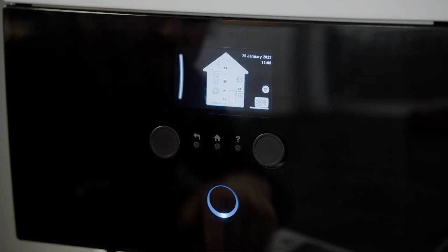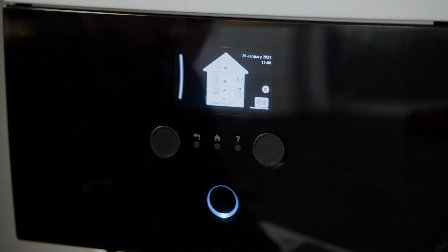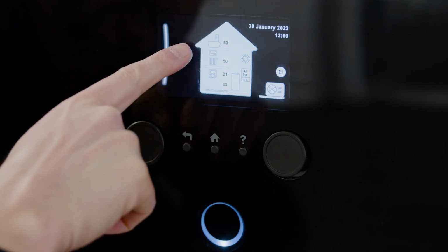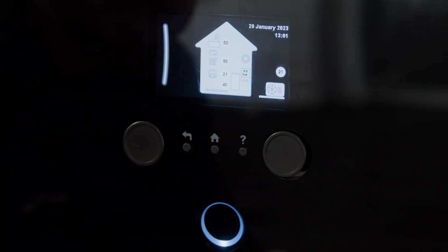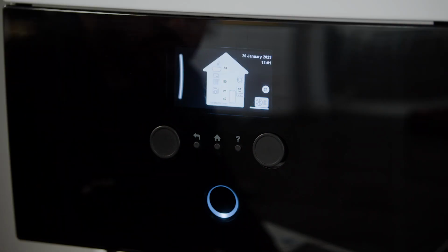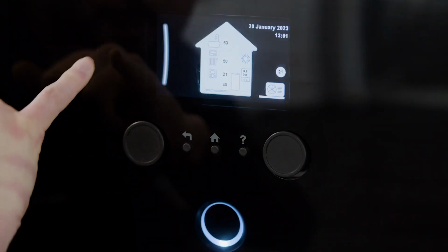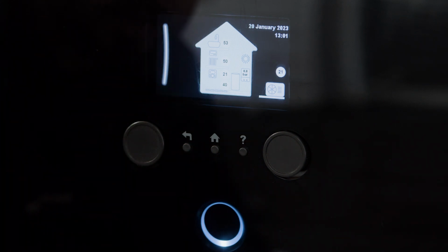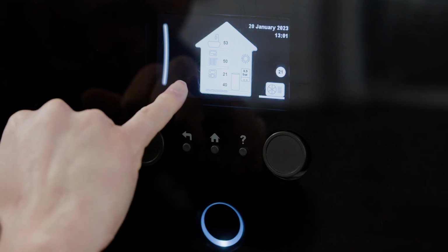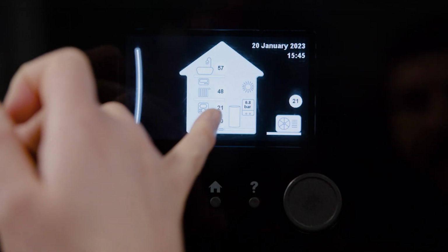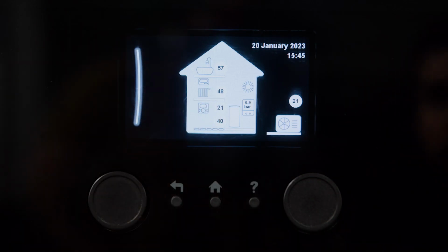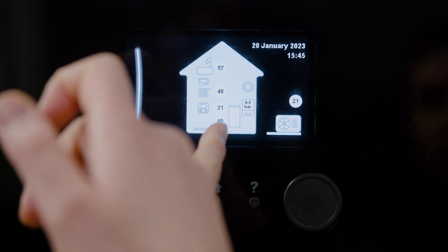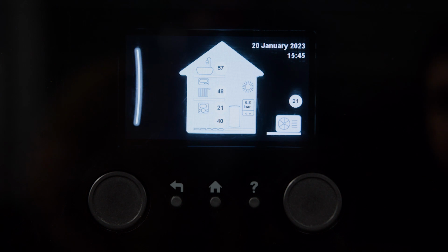There are some sensors within the system, which means that you can see the status or the temperature. For example, next to the bathtub you will see a temperature of 53 degrees. This indicates that the hot water at the moment is at 53 degrees centigrade. You can also see an icon for the radiators with 50 against it. This shows the water temperature going through the radiator. And then you can see the thermostat with the temperature next to it, which is the room set point. The temperature below that, which is 40 degrees, is your leaving water temperature at the moment.